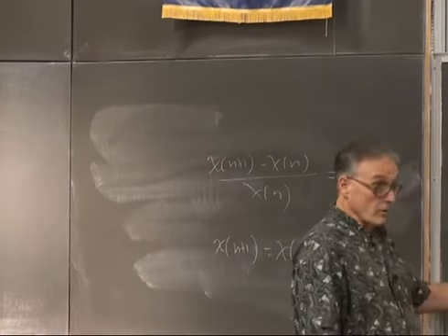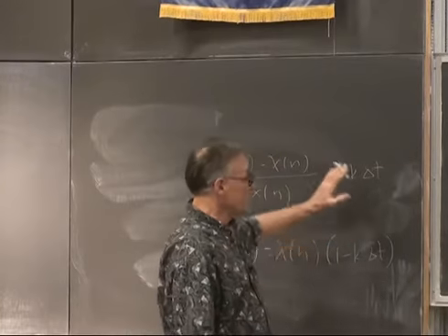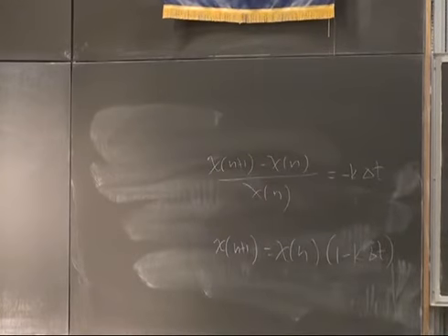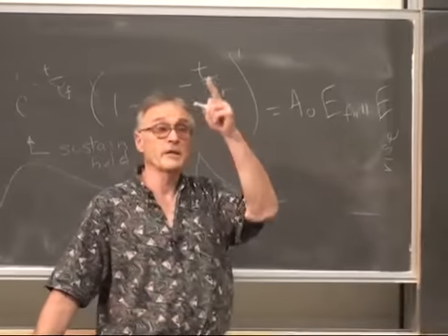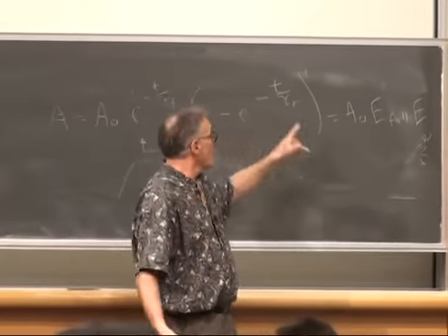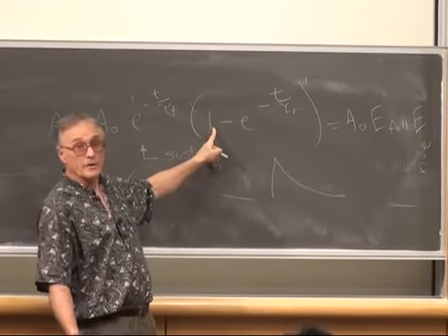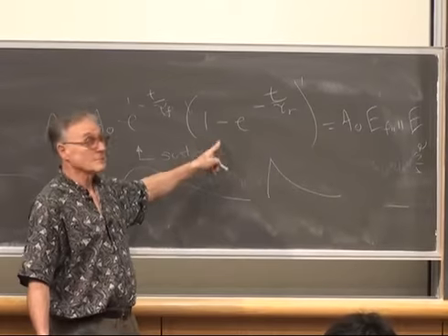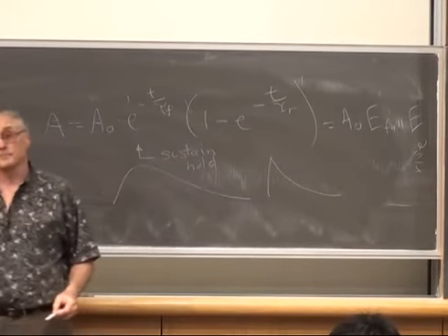So what we're going to do then is use this system once for the fall time. We're going to use a similar system again for the rise time. We're going to calculate a decaying exponential and then subtract it from 1 to make a rising exponential and multiply them together.